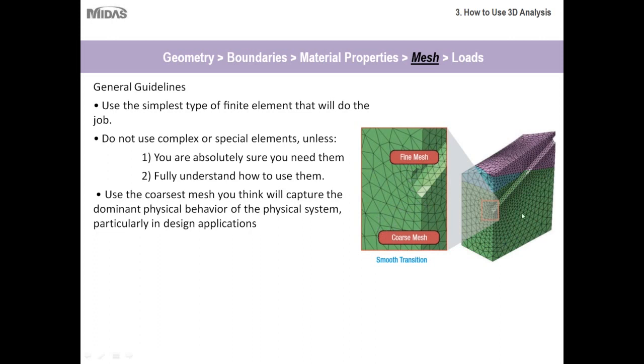As you can imagine, along the edges of this model, the displacements and the strains aren't really of interest to you. You have a better idea of what they'll be. Whereas along the lining of the tunnel and along the opening, that's the area of most interest to you. That's where all the changes, the failures, etc. are happening. So you want the mesh to be finer there, because the more finite elements you have, the more results you'll get, and you'll always want more results for these areas over here.